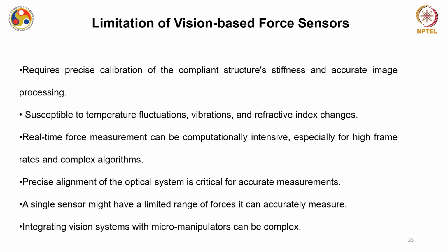However, there are certain limitations associated with this vision based force sensor. It requires precise calibration of the compliant structure's stiffness and accurate image processing. These devices are susceptible to temperature fluctuations, vibrations, and refractive index changes.